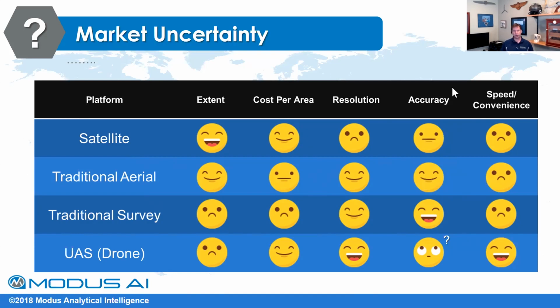And depending if you want to do aspect with a drone, because you can vary altitudes, your resolution isn't just from the top. You can get side scan capabilities, which will not be on par with a terrestrial scanner because their resolution and the ability to sit there for long periods of time is much better. But if you're doing a mid-grade side scan, you're going to get low centimeter resolution.